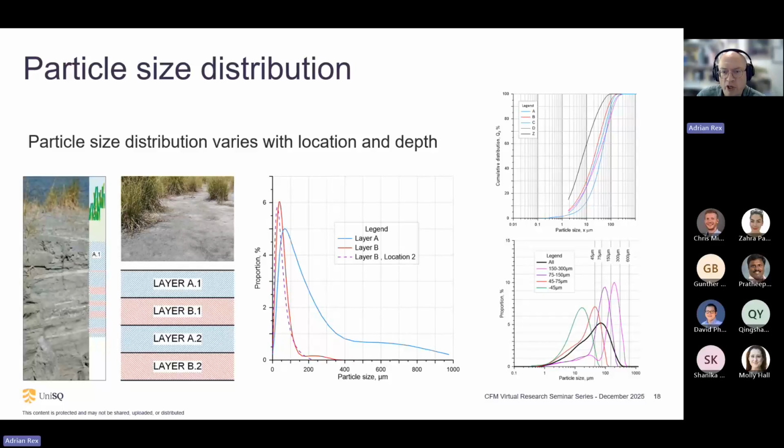They flow across the surface of the pond. Once you stop ponding, you then get evaporation and deposition. So you can see here in the B layer, very, very narrow particle size distribution. As we've pumped there, it's like a beach. We've pumped down, we get coarse particles here and increasingly fine particles as we move further away.